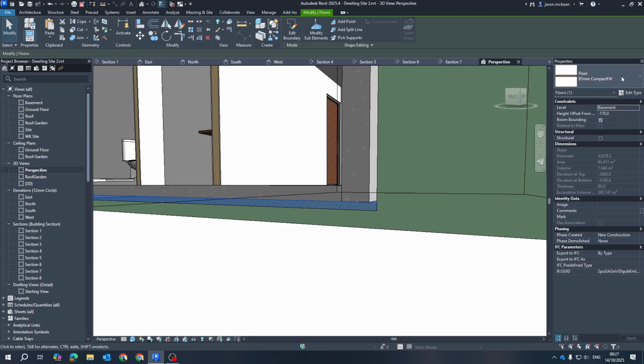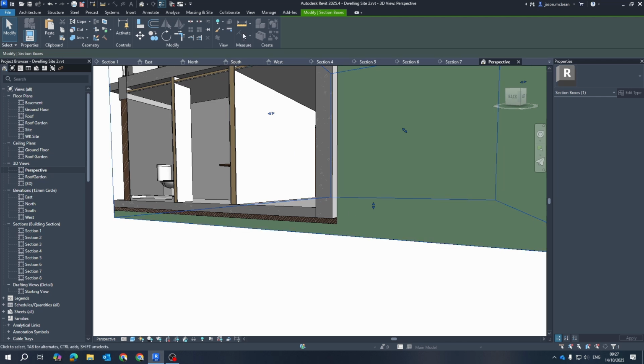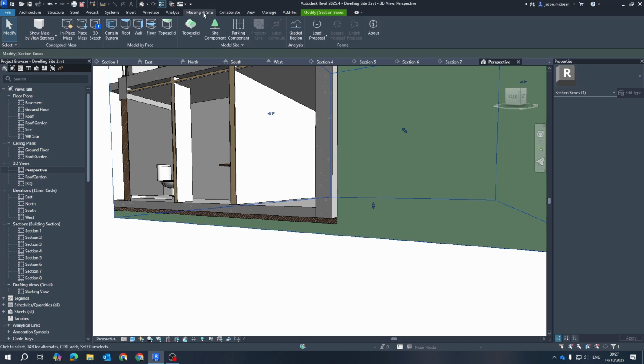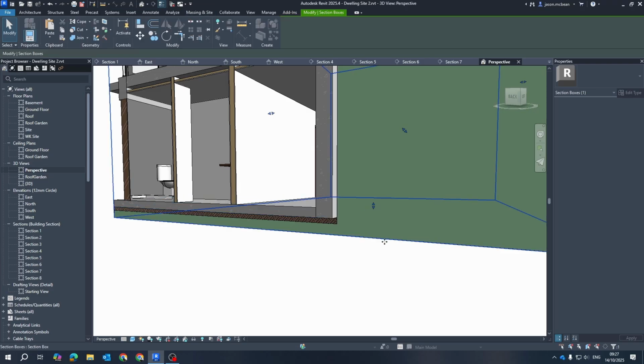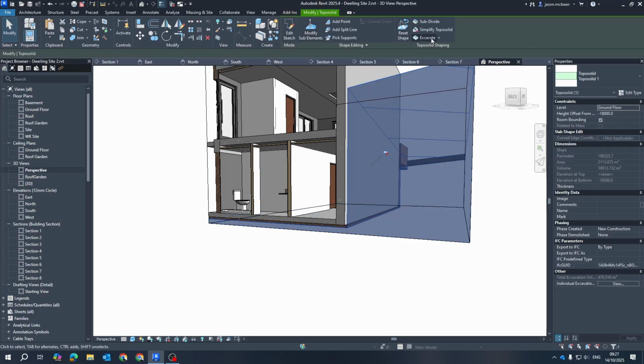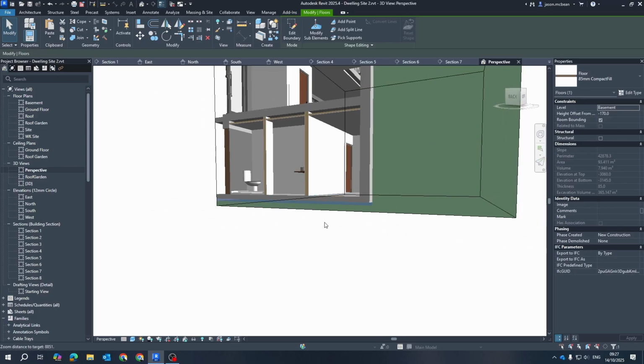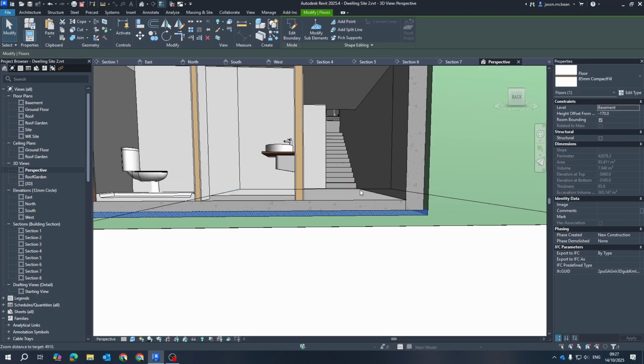So I've used a floor type, that's a fill. I've used that as my excavator. So for my site, you guys did this exercise. If you go to massing and site, let me click on my topography. So I've used my excavate mode. I've used these fills on which the slabs will sit. Remember, there's going to be other detail here.